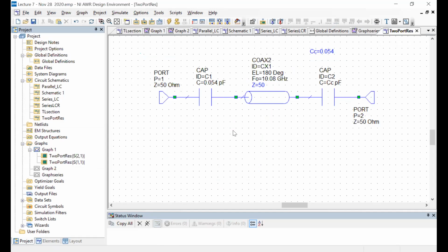I don't think that will be true anymore if there's an impedance mismatch inside, because since there's no symmetry between the two capacitors, there is some sort of impedance mismatch across. So to expect a complete transmission, you'll need to transform the impedance between these two capacitors, and that's not happening here.